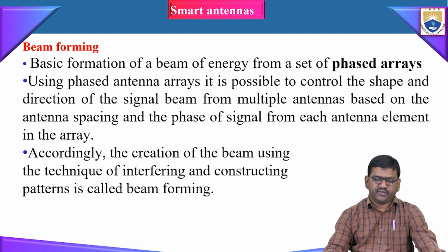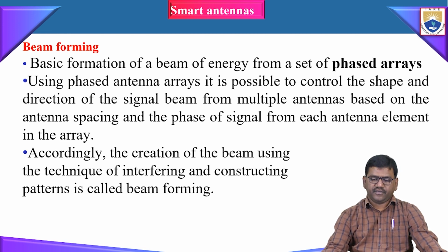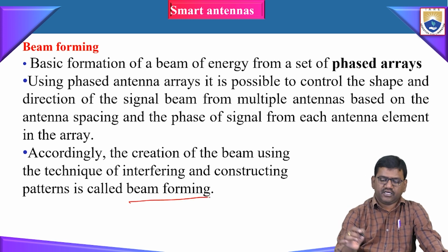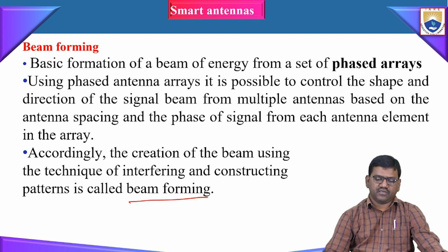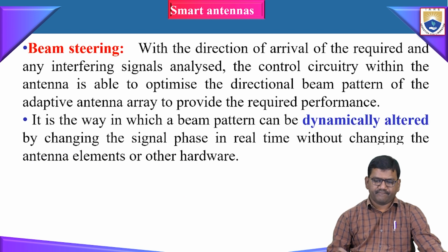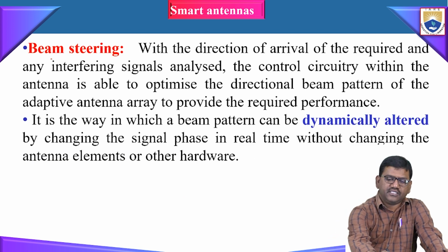So, basic formation of a beam of energy from a set of phased arrays. Using phased antenna arrays, it is possible to control the shape and direction of the beam from multiple antennas based on the antenna spacing and phase of the signal from each antenna element in the array. The creation of the beam using the technique of interfering and constructing patterns is called beam forming.